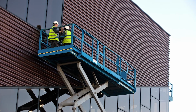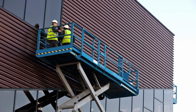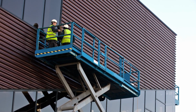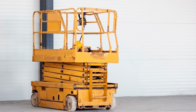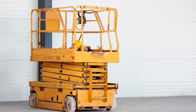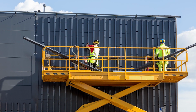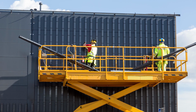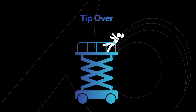To prevent falls, scissor lifts must be equipped with guardrails on all open sides following OSHA guidelines. Guardrails should include a top and mid rail. Before working the scissor lift, the trained employee should make sure that the guardrail system is in place and stable. Workers must never stand on the guardrails. All materials should be kept on the platform, and the worker should never attempt to lean over the guardrails to reach an area.